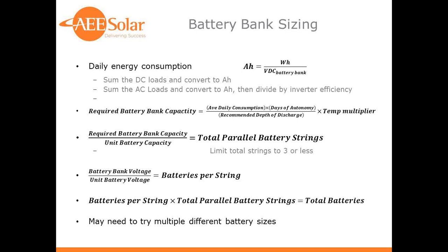So whatever pathway between the negative and the positive post of the batteries to the outputs has the least resistance is going to be where the majority of the current flow is going to be. Now, as current flow goes up, the effective resistance increases, and current will then start to use a higher resistance pathway, and there will be some equalization. But still, you do get some imbalance with any parallel stringing.